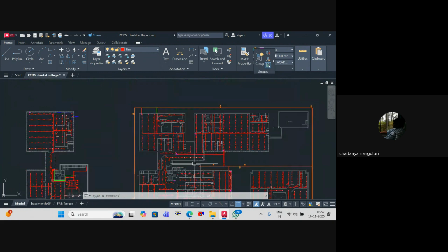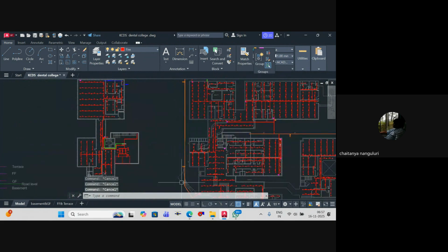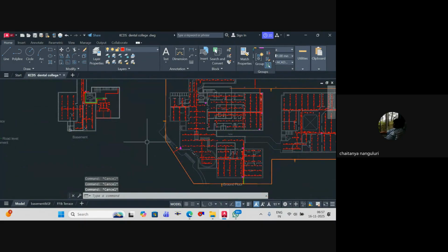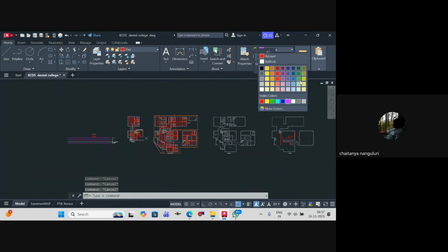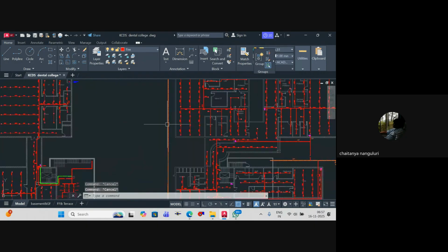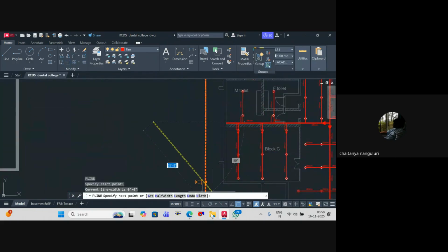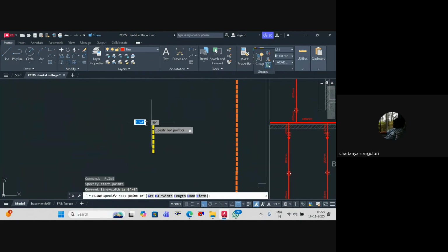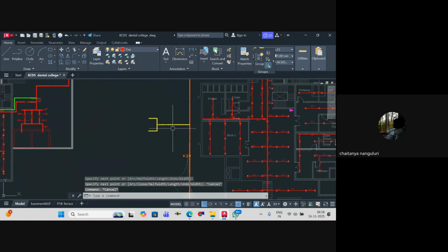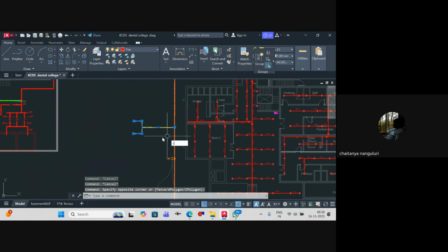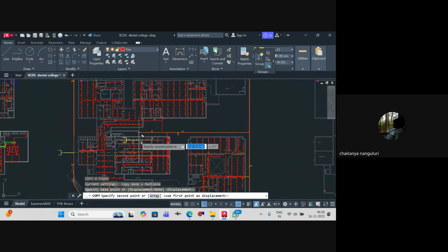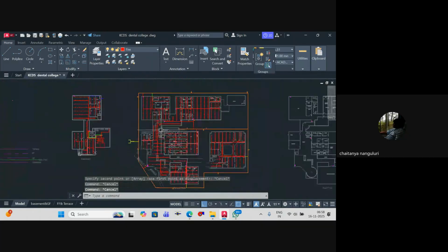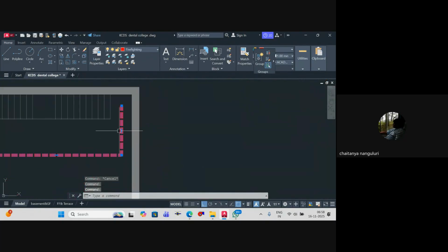So we have to provide to external yard hydrant, and you have to provide even to your tank as well. So if you want external, wherever the nearest entry point is, you will take a stub and you will take it from the top. I'll just show you here. I'll mark it with another color. Let's say yellow. So you'll have your four-way header valve over here. You will have your yard hydrant at this location. One is at this location, and the other one you have to locate near your tank. So tank means obviously it has to come through this location in this case.